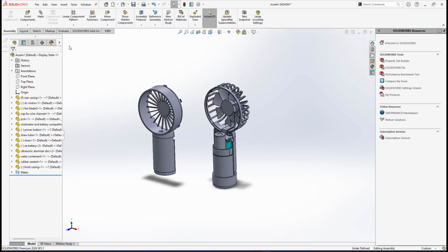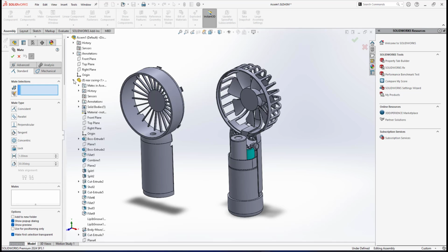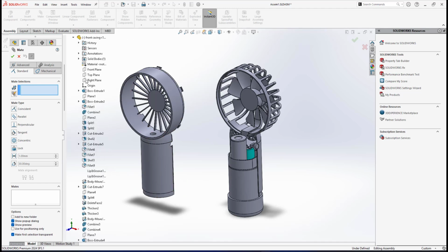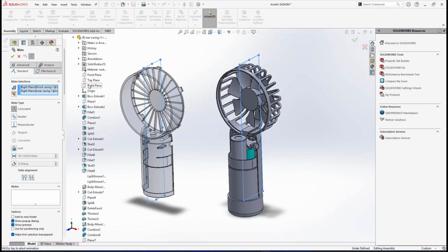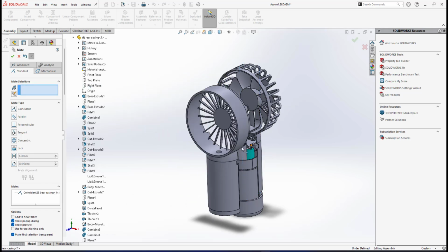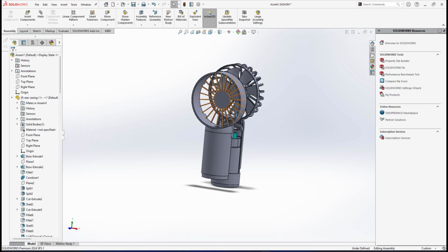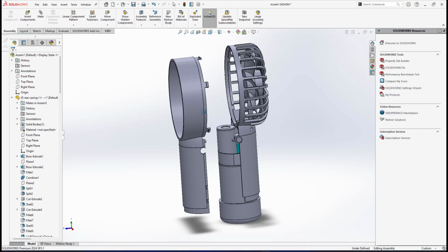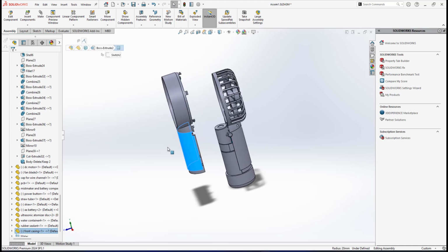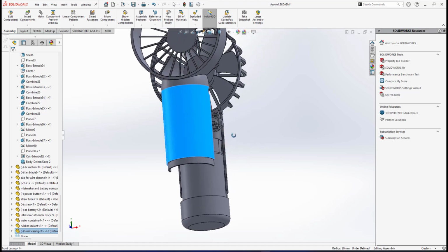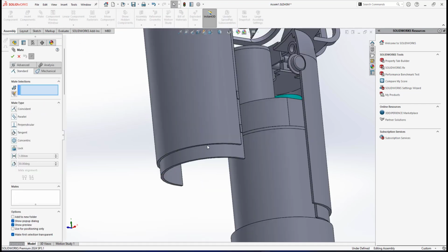Right. Okay, first setting for my front casing is that I will go for this front casing. Let me turn this thing off. The front casing right plane will mesh with the rear casing right plane, so it is kind of in line, right? It's in line. Okay, let me click OK, but my laptop is running a little bit slower. Okay, I can still drag up and down, but it's maintained in line of right plane. Okay, another setting is that I can go for this mate of this surface here.